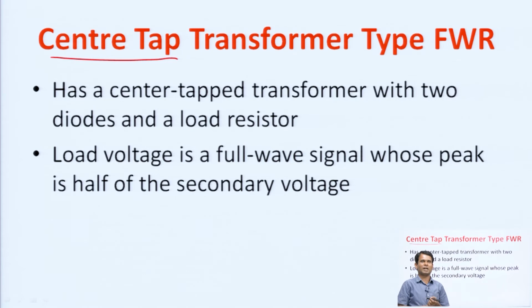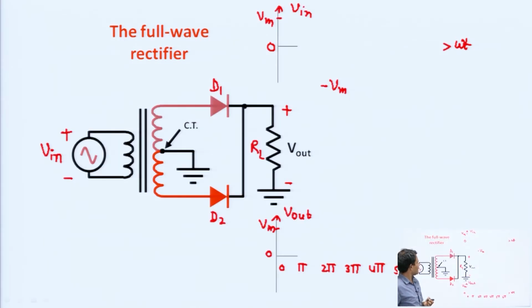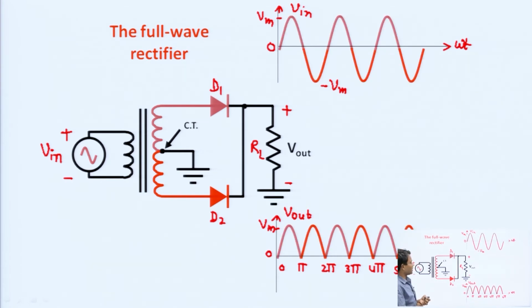This means if there are 200 windings in the secondary winding, then we divide these windings into 2 equal parts, one part of 100 turns and another part having 100 turns. Voltage is divided into 2 parts. If 220 volt is divided into 2 parts, then one half voltage is 110 and another half voltage is 110 volt RMS value. So, this is called the center tap transformer. Now, this is the circuit diagram of the center tap transformer.